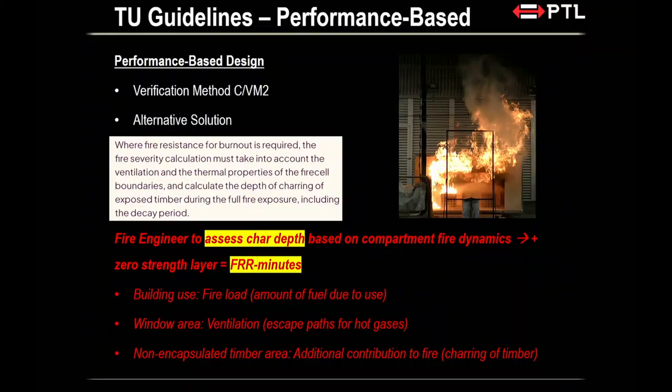But not always. Sometimes you trip into performance-based, and it's quite easy because if you have interconnected floors, for example this university here, all floors are interconnected. The interconnected floor area is too big, or if this is a hospital, we have managed evacuation. Automatically, I have to start doing performance-based design. There's no latitude for me to just read the table and be done with it.